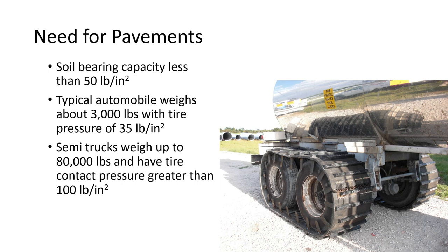and especially in northern Indiana, our soils are not strong enough that you can just drive on them with standard tires. And so the whole point is to spread the load out through the pavement. So by the time that force radiates out of the tire through the pavement and contacts the soil underneath, that pressure is below what the soil can handle. And so then it's safe and it doesn't fail.